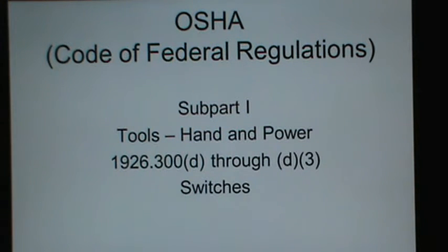Your handheld power drills, your tappers, your fastener drivers, your horizontal, vertical, and angle grinders with greater than 2 inches in diameter, disc sanders, belt sanders, reciprocating saws, saber saws, and other similar operating tools shall be equipped with a momentary contact on-off control and may have a lock-on control provided that the turn-off can be accomplished by a single motion of the same finger that turned it on. Okay, you're probably thinking about your tools right now. Sure, they probably comply with this.